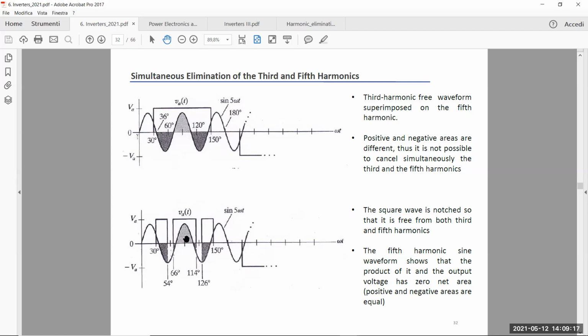In effect, if you remember the output spectrum of the voltage for a pulse width modulator, you have F1 and the first high order harmonic around the switching frequency Fs. So this means that you can come back to something that we already know. But for some specific applications, it will be easy to have small notches, so not increasing too much the switching frequency and the dynamic losses of the transistors, but anyway making easier the simulation and the design of the output filter.